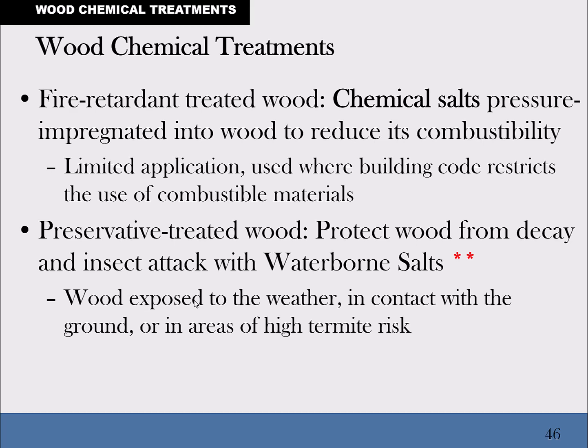So we typically, the only pressure treated lumber you're supposed to have on a typical house is the bottom plate. You can do the bottom plate because there will be some shrinkage level that's going to happen there that can start tearing apart a house. If you were framing a house with pressure treated lumber, you're in for trouble.